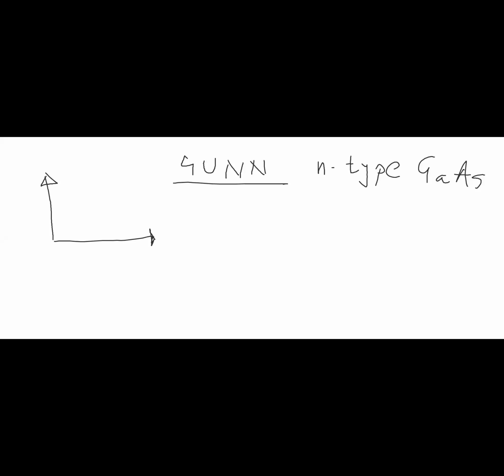Okay, so first, what he observed: the x-axis represents the electric field. This electric field was applied across a sample of N-type gallium arsenide. The specimen which was used was 2.5 × 10^-3 centimeter in length. And the vertical axis represents the velocity of the charges in the gallium arsenide.